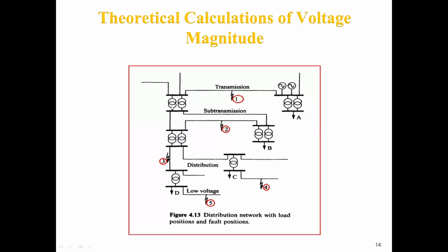So the impedance of the transformers is considerable enough to limit the voltage drop at the high voltage side of the transformer. The sag experienced by customer A is further mitigated by the generators feeding into the local transmission substation.